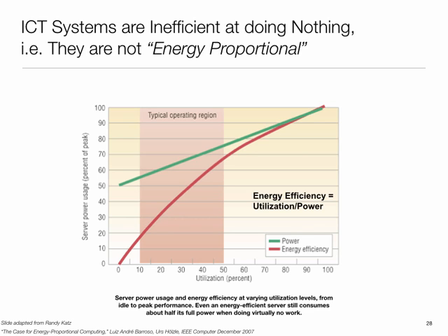Yeah, leakage. So DRAM stores data. DRAM is what the bulk of the memory is. DRAM stores data in capacitors. Those capacitors leak, and therefore every few tenths of a millisecond that data is rewritten, which is why DRAMs burn power. So you have to maintain their state. Okay, so that's one. You have to keep the state.